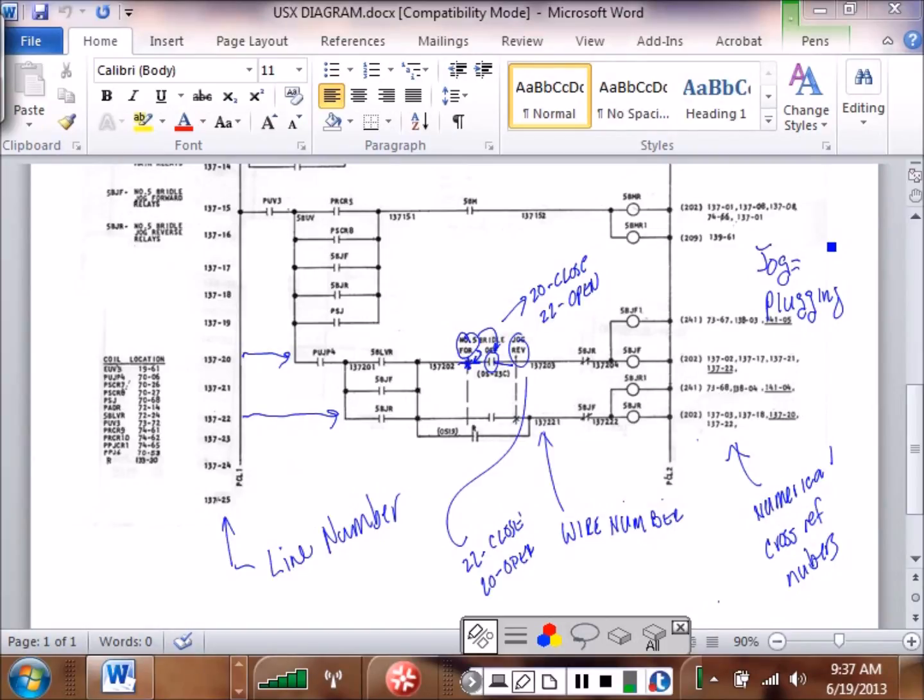Anybody got ceiling fans in their house? You ever go up there and reverse them while they're running? What does the motor do while it's trying to reverse itself? There's just a humming, right? So you can tell that motor's pulling a lot of current. And of course, you're going to decrease the life expectancy of the motor. So plugging, some motors can be plugged, some motors can't be plugged. It basically deals with something we call a service factor that we'll deal with.